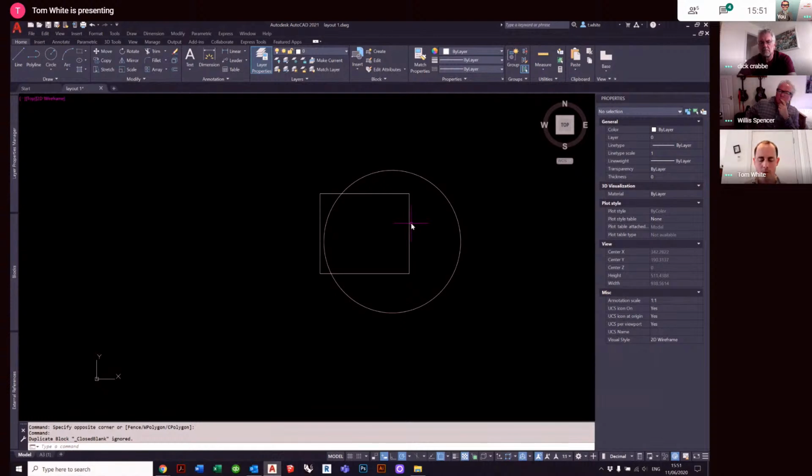And the nice thing about going to XREF, particularly if you've got 5 or 6 DWGs in there, is that if you select them all and hit bind, you'll just see them disappearing as it pulls them into the drawing, and you'll end up with what Tom has, nothing. You'll just have the drawing name and nothing in it, and everything is definitely inserted in the drawing.